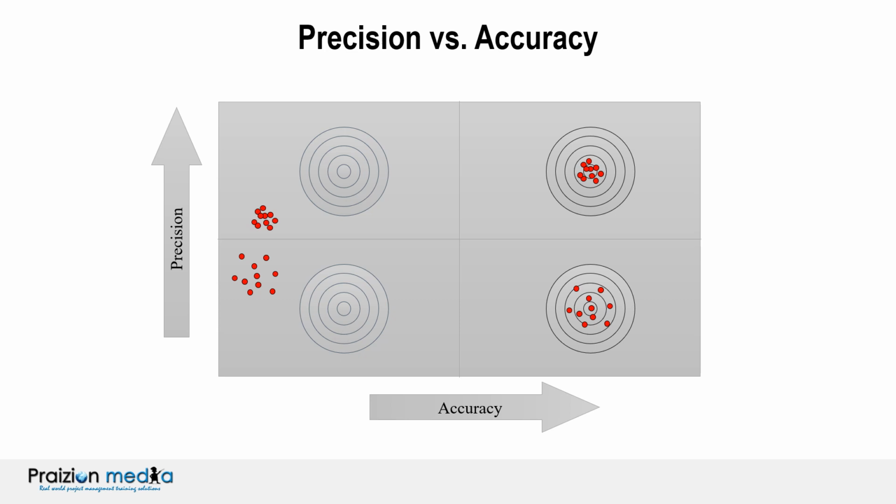I talked about this to demonstrate what happens in our actual measurement systems. Measurement system is the key to your measure phase. If your measurement system is faltering, it may tell you that you are producing good, or that your operation is fine. That is living in a fool's paradise, a false sense of security. And if the measurement system is bad and you are actually producing good, again you are at a loss. You are rejecting your good parts. You might be in two situations: supplying bad parts to the customer thinking they are good, or rejecting good parts thinking they are bad.